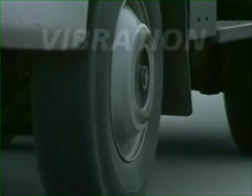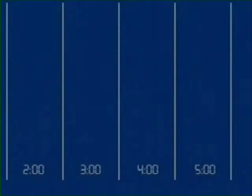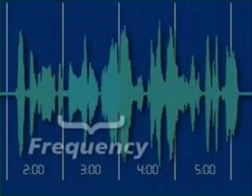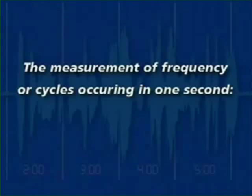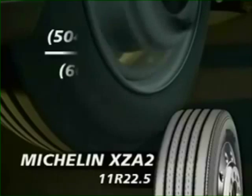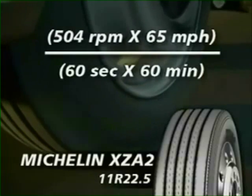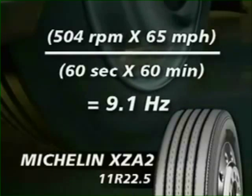A vibration has two characteristics: frequency and amplitude. Frequency is defined as the number of repeated motions which occur in a given period of time, usually 1 second. The measurement of frequency, or cycles occurring in 1 second, is commonly referred to as hertz. For an example of frequency, an 11R22.5 Michelin XZA2 will rotate 504 times in 1 mile. Thus, at 65 miles per hour, the frequency, or hertz, for this tire is 9.1.